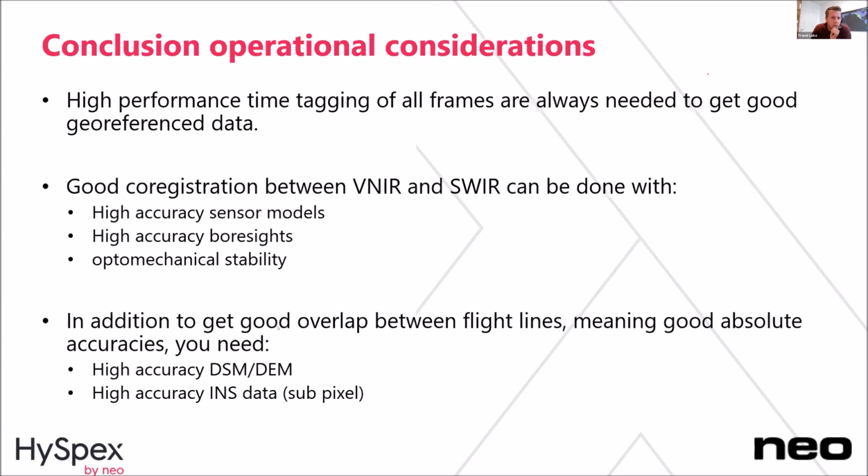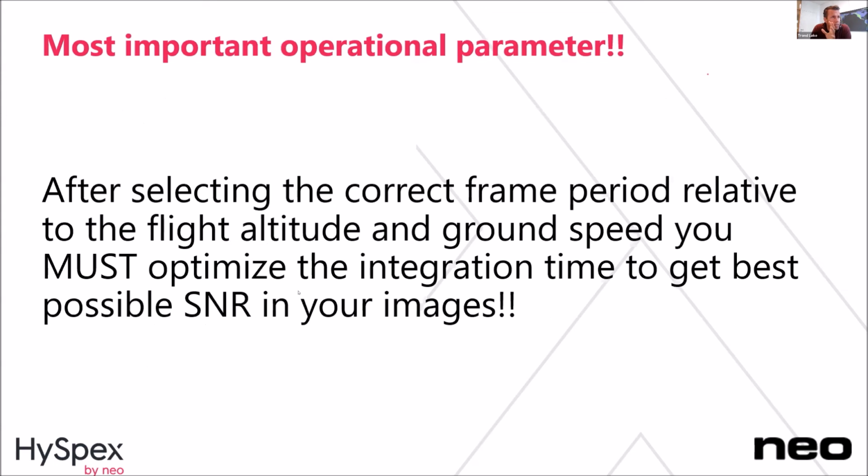Yeah, and then at the end for this, another very important operational parameter that I almost don't need to mention because it's obvious, but I'm doing it anyway. After you have selected the frame period relative to your flight altitude and ground speed, I think Agnar will mention something about that later, about the flight planning, you must optimize your integration time to get the best possible signal-to-noise ratio in images.